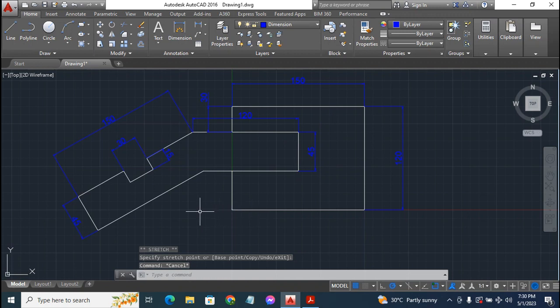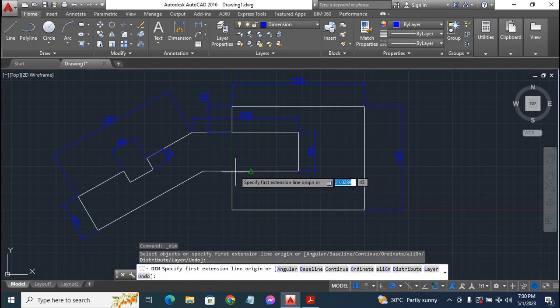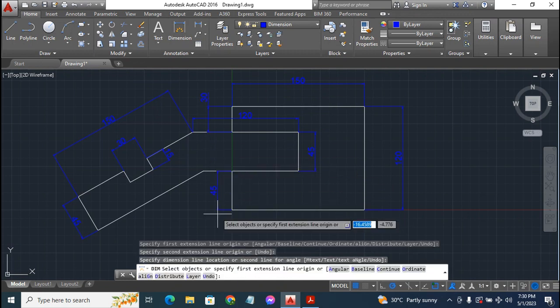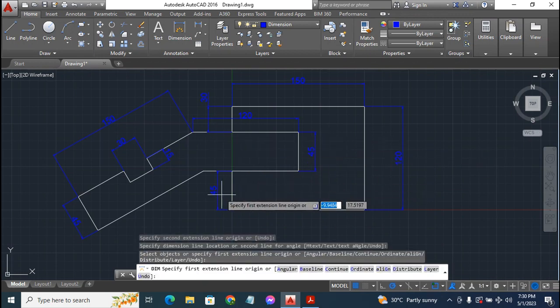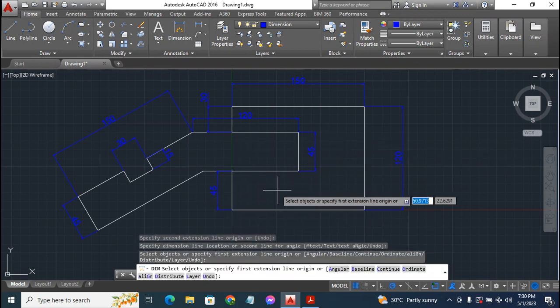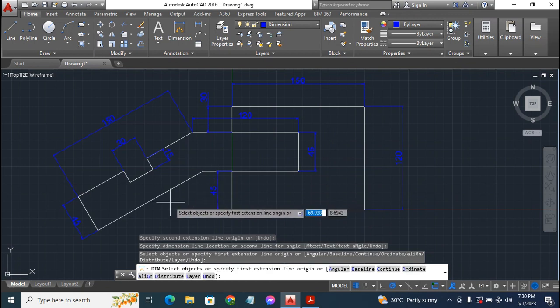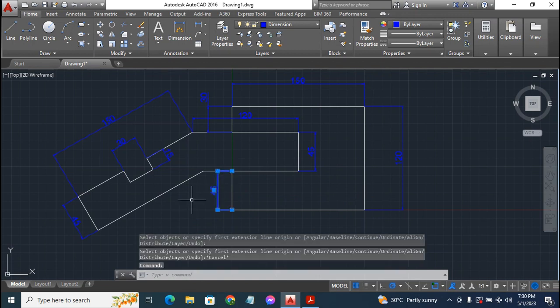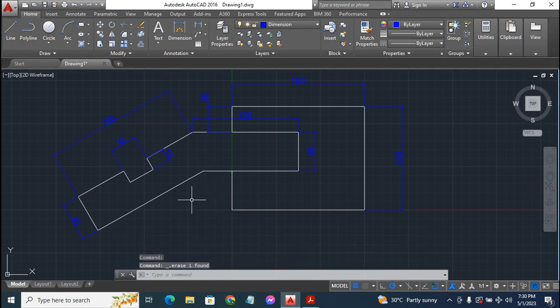All right, so let's still put in the dimension between this base and this very point. That will save the machinist some stress. So let's do that. Yes, 45. No, let's put it in the other direction. We kind of get in the way of the angular dimension we need at that point. So let's get rid of this. Click on it and press delete on your keyboard.